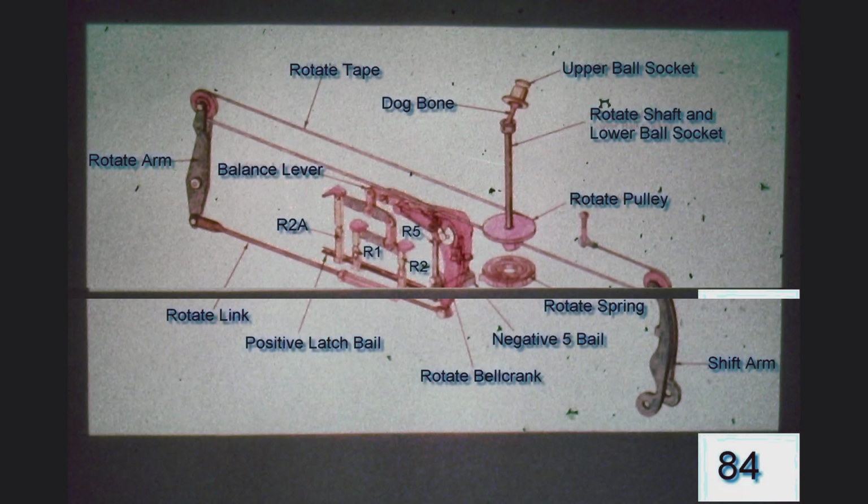Let us summarize all this. To obtain one rotate increment, the input section, or keyboard, leaves the R1 latch under the positive rotate bail while filtering out the other latches. To obtain +2 rotate increments for the element, the input section leaves the R2 selector latch under the bail while filtering out the R2A and R1 selector latches.